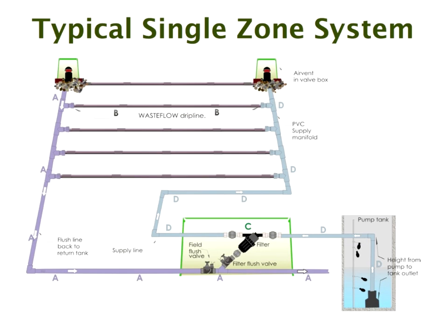Okay. We're now going to really talk about installation, which is, I think, the main topic for the day. And of course, you've got to install the pump tank, and there's got to be some form of filtration. And then we will pump out, then they're going to have your supply lines and your manifolds, your air vacuum relief valves, then your drip lines, and then your return, in which case it's shown nicely going back to the pump tank.